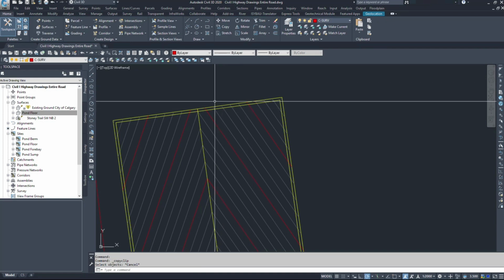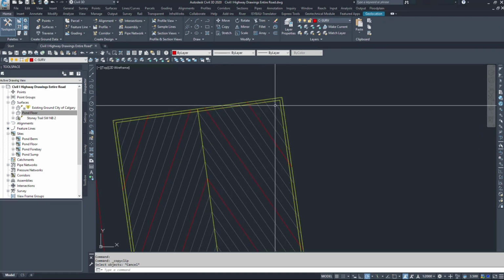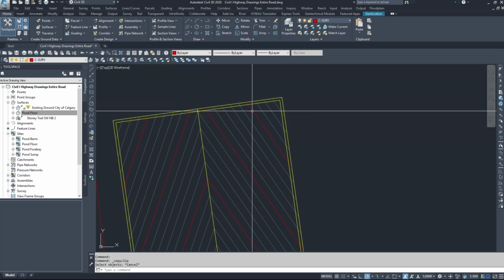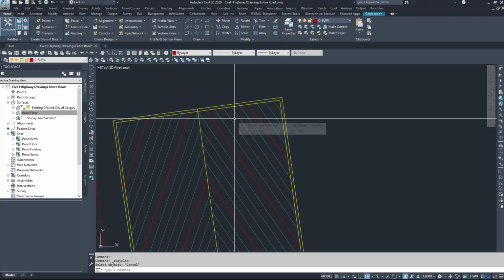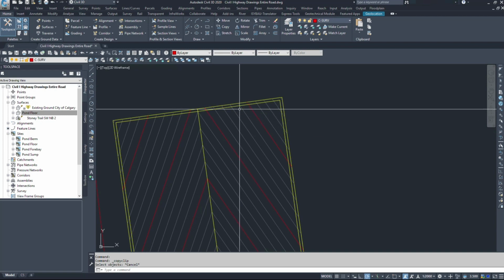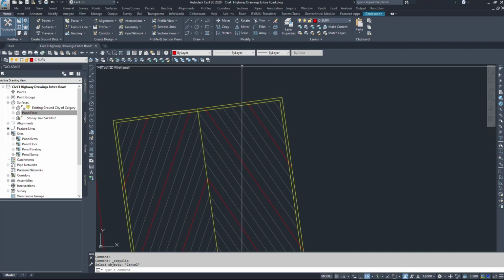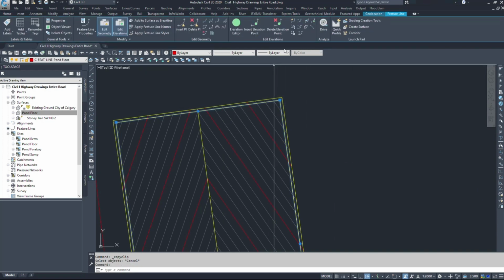Now, when we build the pond floor, we need to include it inside what will be our pond berm so we can target things properly. And the top of the berm I want 3 meters wide, so I've gone 1.5 meters on the inside, and I'll do 1.5 meters on the outside. But we'll do the 1.5 meters slightly different.